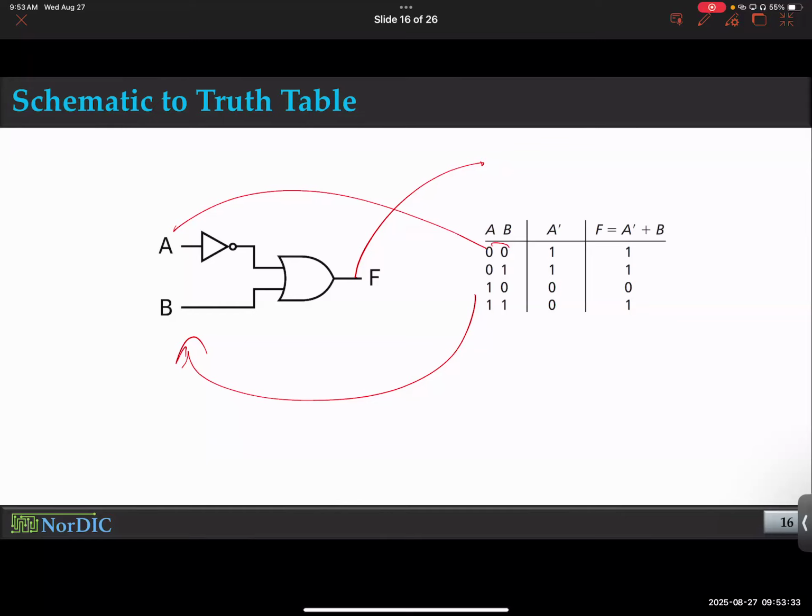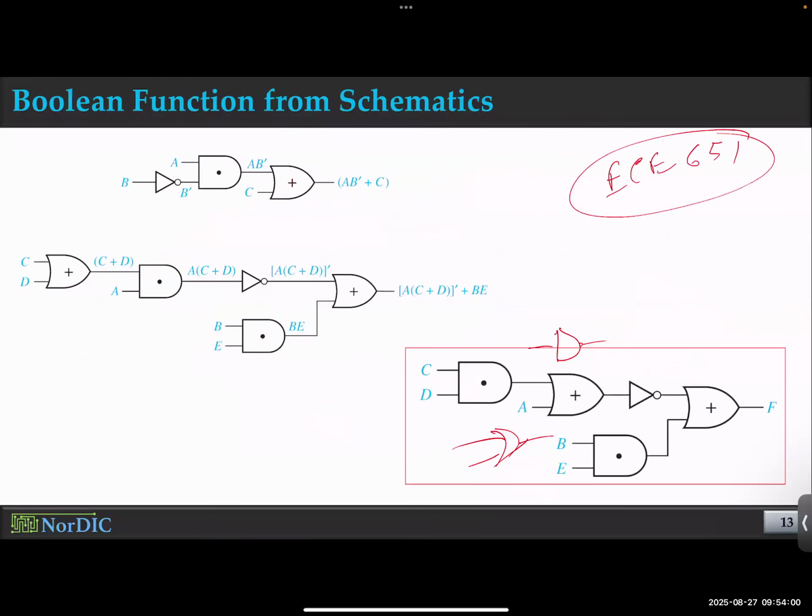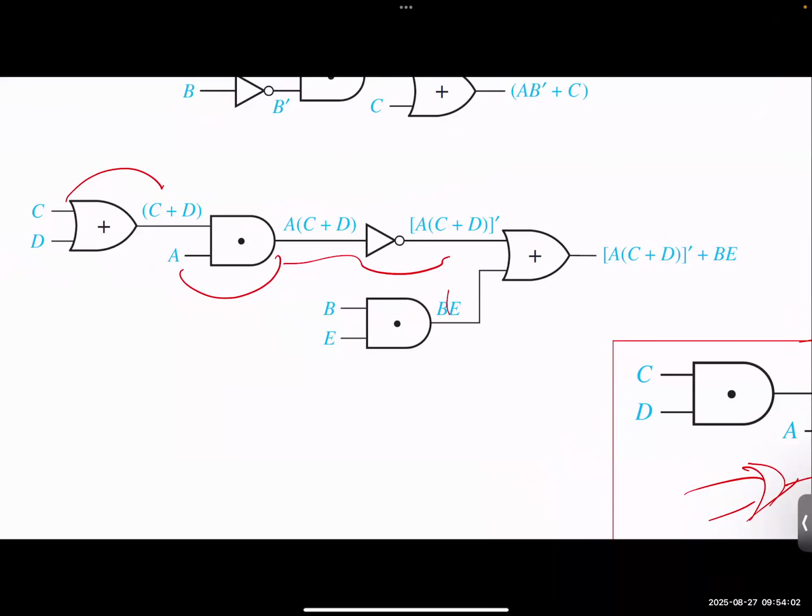And you keep providing 0, 0, 0, 0, 0, 1 in the inputs. Make sure you go through all the combinations, row by row, and you just measure the output. Interestingly, the output could only give you 0 or 1. You just measure the output and you populate this truth table. And I will show you in the next lecture, given a truth table, you can figure out the function. So you don't have to do what we did here, go through every stage. No. You can directly generate the final output given the truth table. Are you still with me?